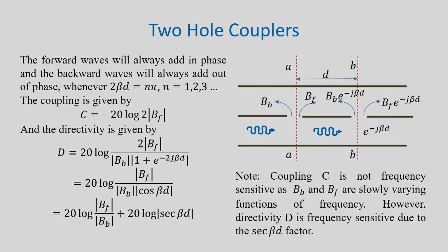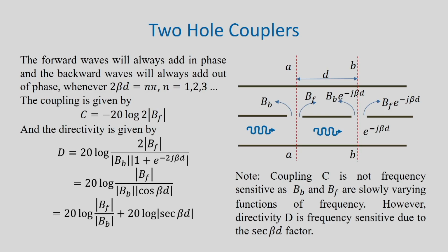We should note that the coupling C here is not frequency sensitive, as B_B and B_f are slowly varying functions of frequency. However, if we look at the directivity term, the directivity D is frequency sensitive because it has this factor sec beta d.